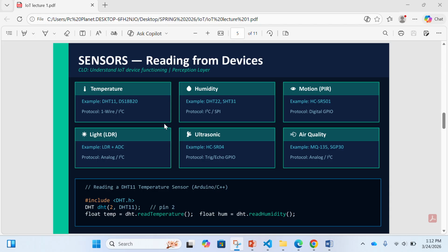Once a sensor has a reading, it needs to send that data to the microcontroller. It uses one of several communication protocols. So what are the communication protocols? GPIO pins. GPIO digital: one signal wire plus ground, single high/low pin read, such as a PIR motion sensor or button. Analog: one signal wire plus ground. I2C: SDA plus SCL plus power.